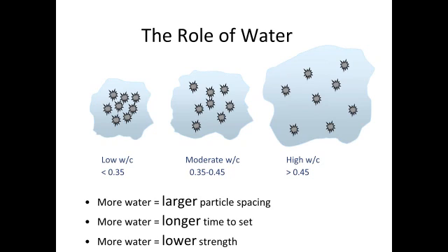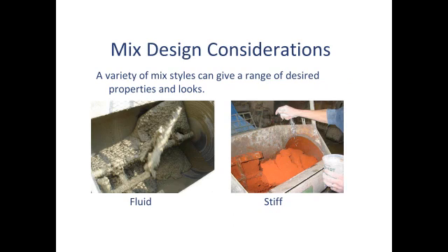Likewise, as you add more water, everything gets spread out and diluted, and now instead of being a tight solid, it's more like an open, fragile sponge. And it's that open, fragile sponge that makes weak concrete, that makes porous concrete, that really you can't recover from. And so superplasticizers kind of are a sleight of hand, if you will, that lets us have really good concrete that normally would be almost impossible to work with, but make it have the fluidity that we want.